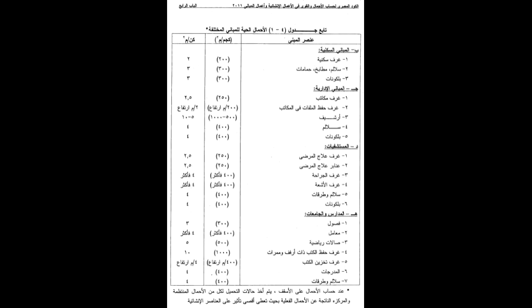In administration buildings, which have offices, the office live loads will be 250 kilograms per square meter. The loads for archive, for filing and things, usually having a lot of shelves to store the files. So the paper is heavyweight.